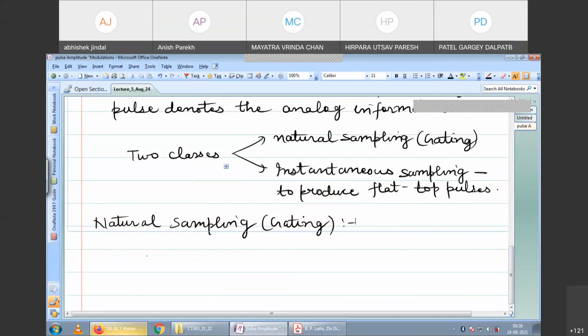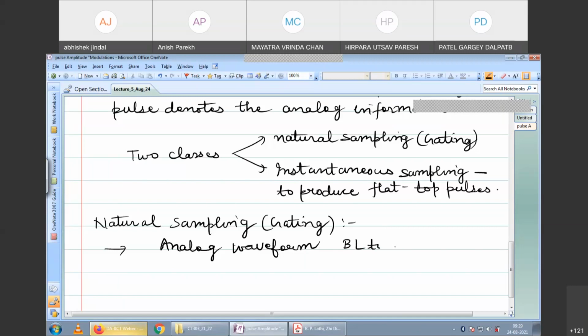Let us move ahead. So we start with an analog waveform. This is important because after studying sampling, we know that the concept of the signal being band limited is the heart of sampling. You can say that the high frequency components are of very low power. Right now we are ignoring the issue of time limited and band limited, because we know how to handle that in reality. For the theoretical analysis, assume that the analog waveform is band limited to B hertz, and we call it w(t).